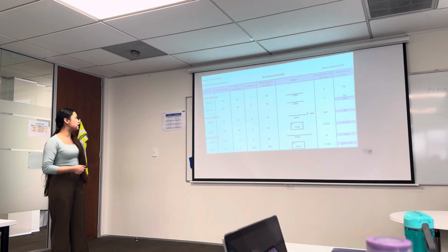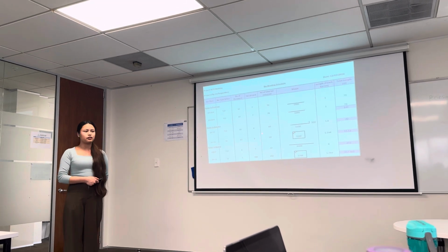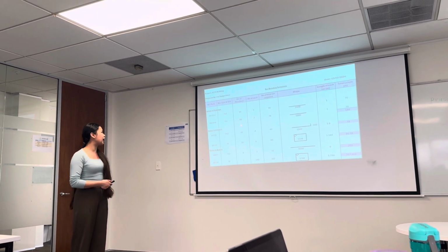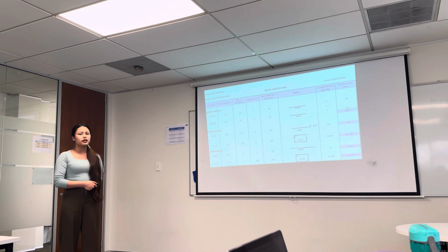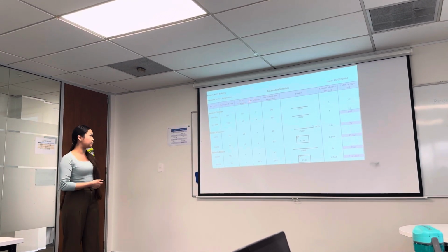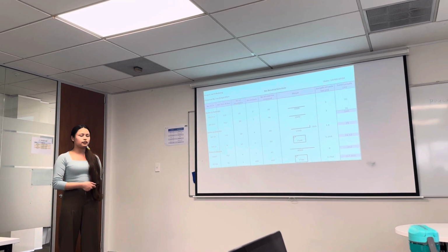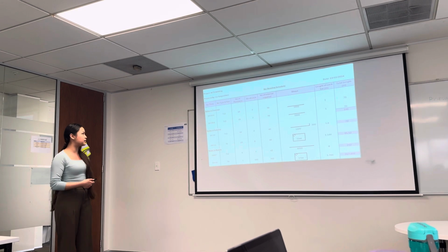And bar type and size T12, T12, T6, we are saying that this is the diameter of the bar that we are using. And the number of members, like the footing is coming 10 times, so we consider 10 times here, and the number is 7. We can say in the drawing, it's clearly mentioned in the drawings.